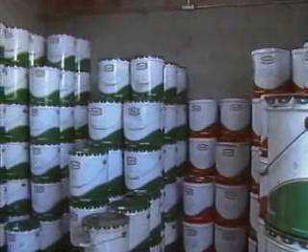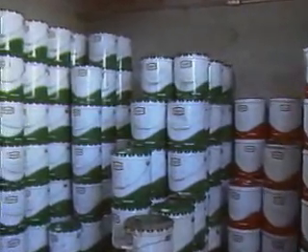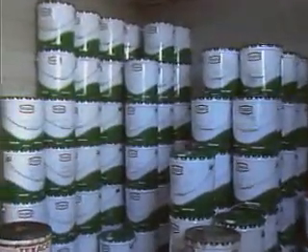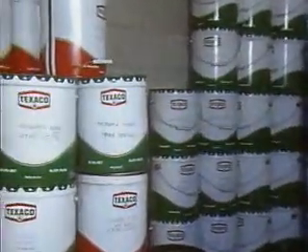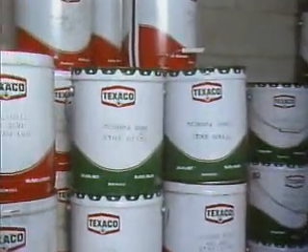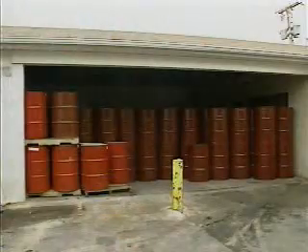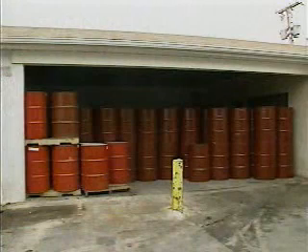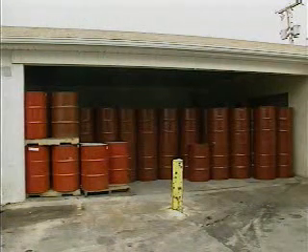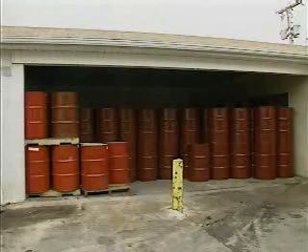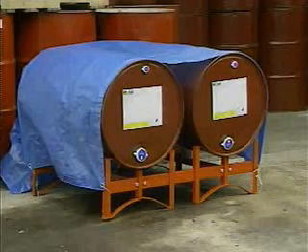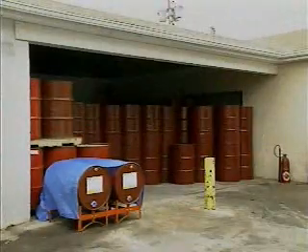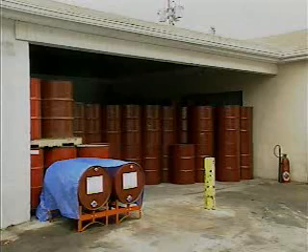After lubricants have been delivered, they're often stored in their containers for a long time before they're used. Depending on a facility's available space, the containers may be stored indoors or outdoors. Two major problems with outside storage are dirt and weather. So store lubricants in a location where there's a minimum of dust and dirt. Also, use a temporary covering like a tarp or a permanent covering like this three-sided shed to protect the containers